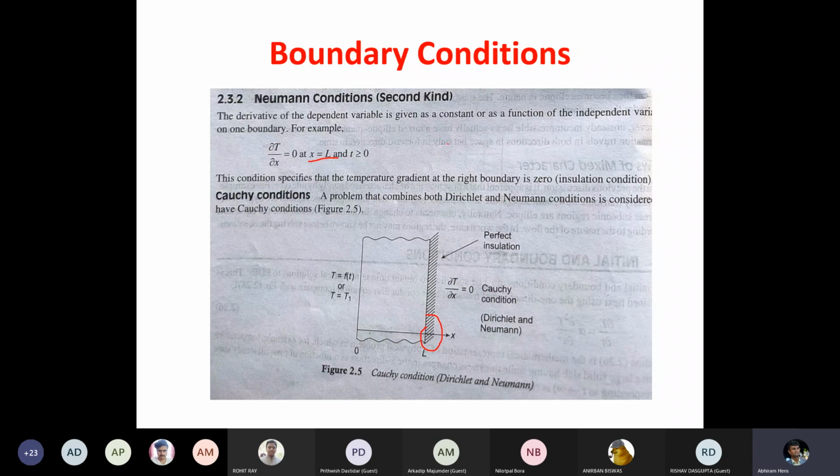Let's say you have a pipe like this, and your flow enters here. We call that the inlet boundary condition, where there will be some velocity, say v equal to 100 meters per second. At the outlet we generally do not know the value of velocity, because that is not required. We just want that there is no more pressure gradient. It's a free surface, where the fluid is just going out and falling into the environment. So here this boundary condition is called dp dx equal to 0.